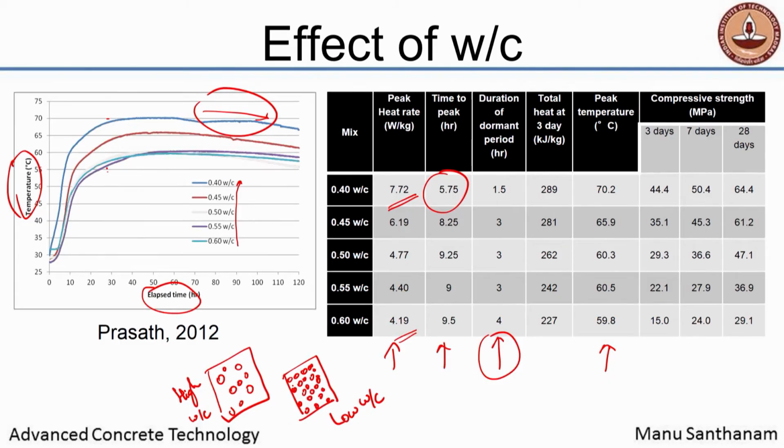Okay. Essentially, the water between the cement particles starts getting consumed to a level that is enough to produce a sufficient amount of hydrate around the cement particles. And these hydrate particles which are around the cement particles start getting connected. That is when we are getting setting. That is exactly the meaning of setting. Okay. So, these hydrates that are around the cement particles need to start getting connected and form a network, and that is basically setting.